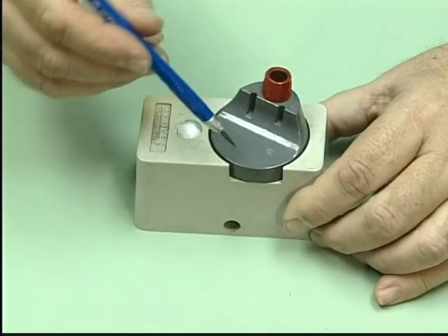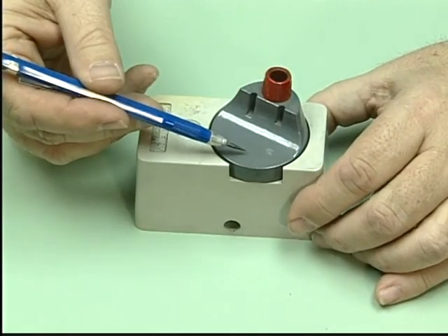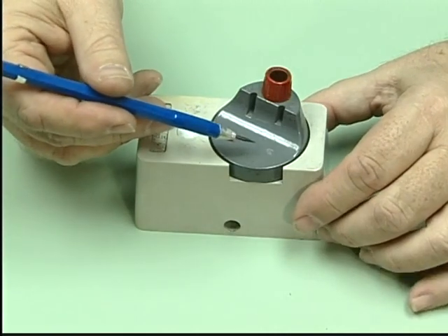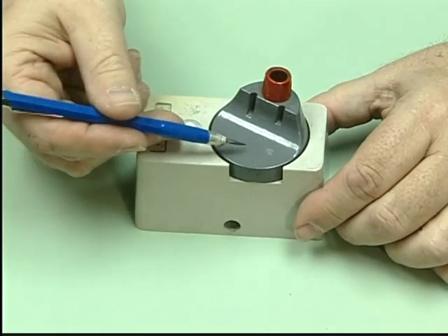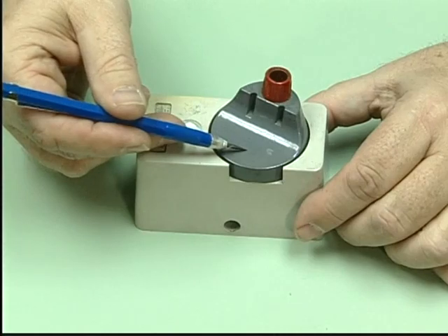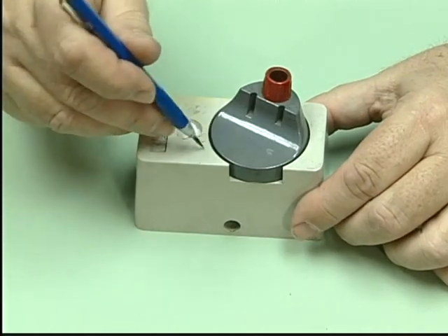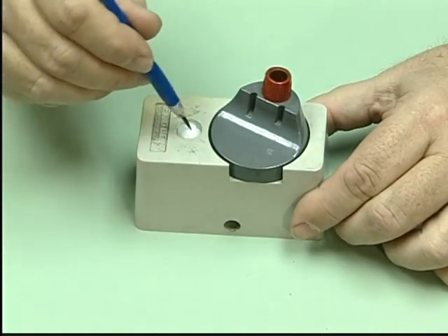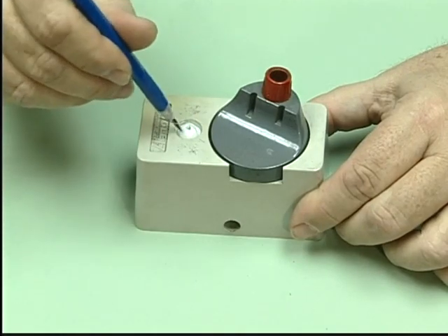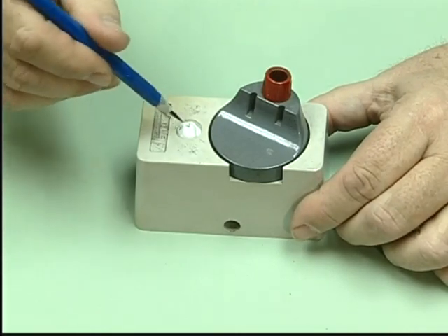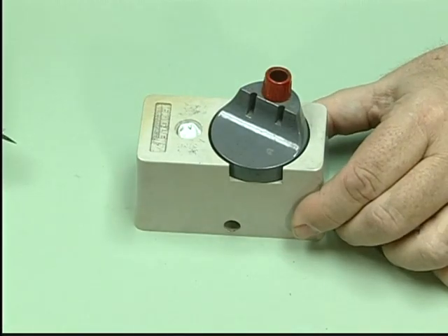Once again, this might be a little too sharp to use and it will have some graphite dust on it. An old drafter's trick: when you first sharpen it, you don't want that little sharp point breaking off when you start drawing, so just tap it a little bit and then poke it in an art gum eraser or this nice little cleaner that's provided here to clean that graphite powder off.